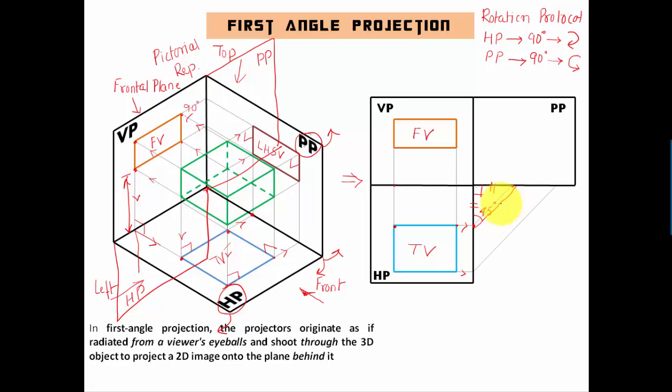That's it. All right, and you're going to go ahead in the upward direction. Finally, you have to draw projector lines from these points, something like this, and it's going to look something like this. And finally, these are the intersection points that you're going to get. And when all these points are joined in proper sequence, you have a view. And since you're looking at this object from the left hand side, you're going to have a left hand side view. So let us summarize all of these things, guys.